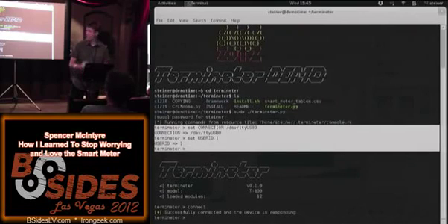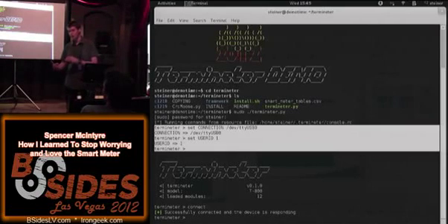When you connect to the device, it's going to show you can log in, and it's going to pull down information from the general config table. The reason why this is important prior to connecting is that different vendors use a different endian mix, and that endian is to be read from the first general config table. So when you connect, it's going to pull that endian mix down and configure itself to use the proper endian mix and packet values.